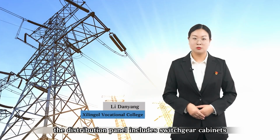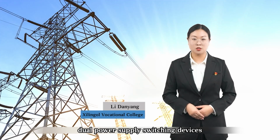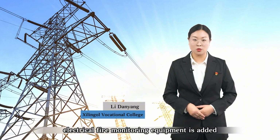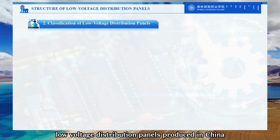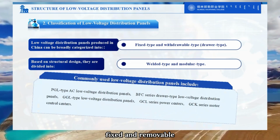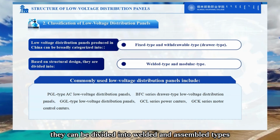In the video, the distribution panel includes switchgear cabinets, capacitor compensation cabinets, dual power supply switching devices, and outgoing line cabinets. Nowadays, in the design of new low-voltage distribution panels, electrical fire monitoring equipment is added to monitor residual current. Low-voltage distribution panels produced in China can be basically divided into 2 types, fixed and withdrawable. According to the basic structure, they can be divided into welded and assembled types.